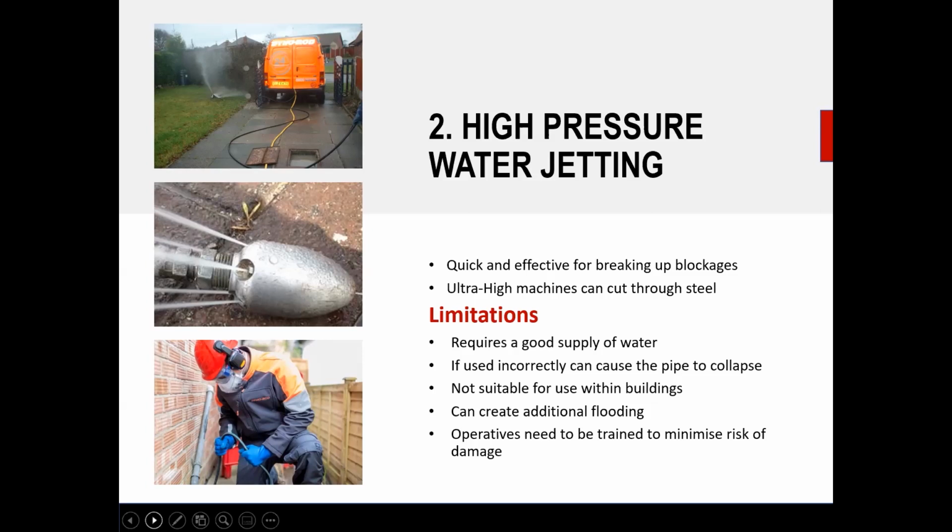So generally the jetting head is designed so it will propel itself up through the pipe, and then when you get to the far end, the operator will slowly pull the jetting nozzle and the jetting hose back out the pipe. So you're actually cleaning the pipe when you're going back through the pipe instead of going up to the far end.